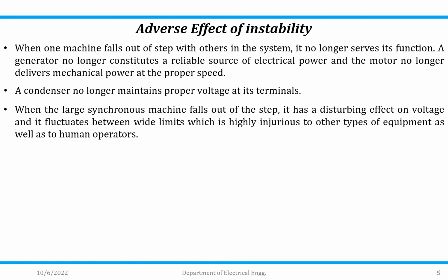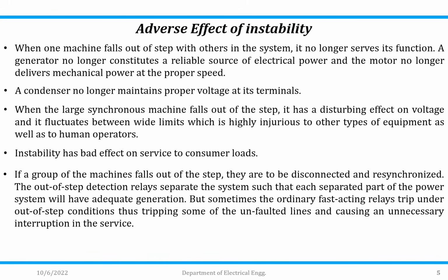Now, whenever a large synchronous machine falls out of step, it has a disturbing effect on the voltage, and it fluctuates between wide limits, which is highly injurious to other types of equipment as well as to the human operators, because most of the equipment is designed to operate at a constant voltage level. Instability has a bad effect on service to the consumer load. So these are the adverse effects of instability.